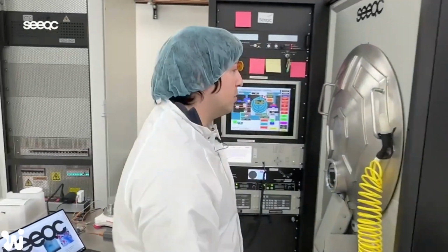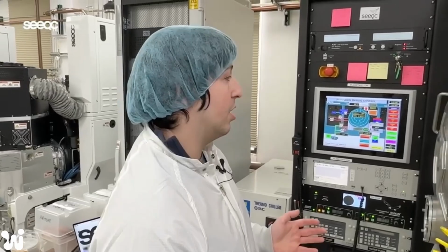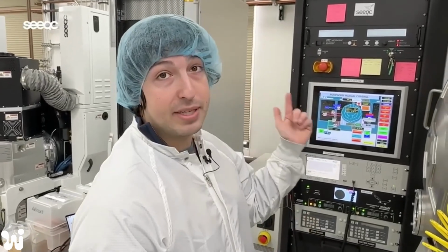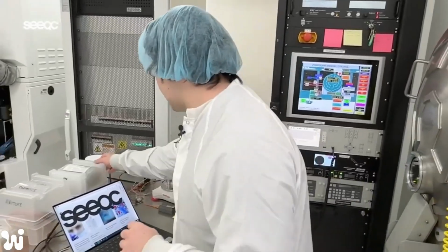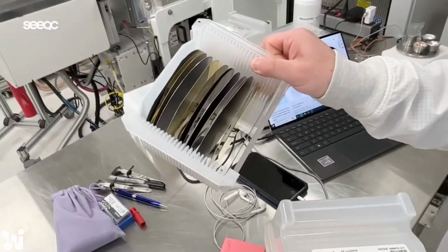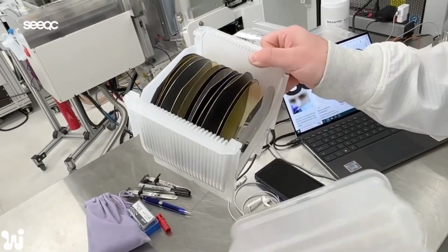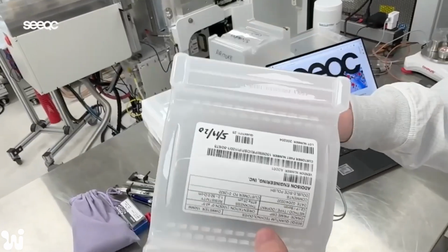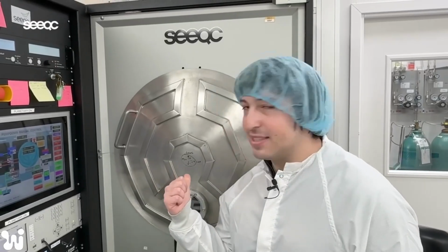We use this tool for our titanium, gold, palladium depositions. It has a carousel on top, so it can do up to 9 wafers at once. You can see here we have some dummy wafers that'll have different layers of metals on them, which we can then use to get the right resistances that we're looking for. Coolest machine, I think this one, because it's evaporating things like gold, metal, titanium, stuff you don't normally get to play with in your everyday life.